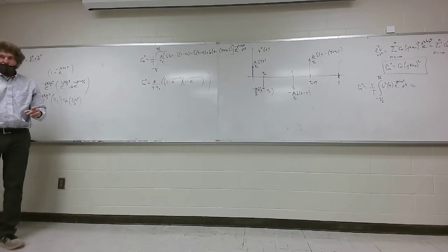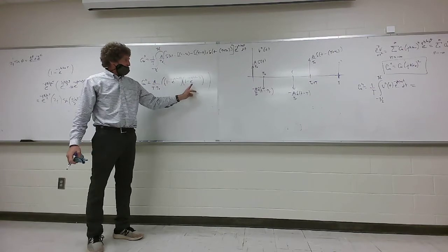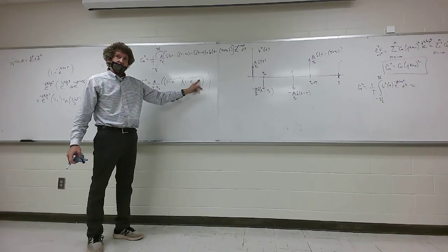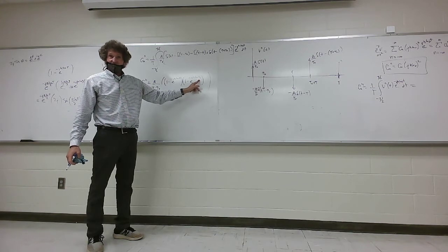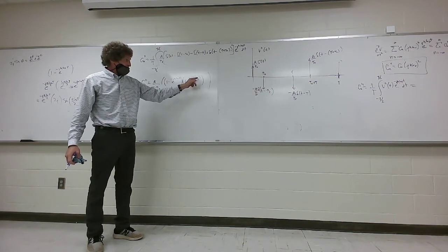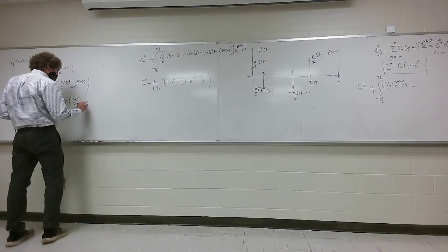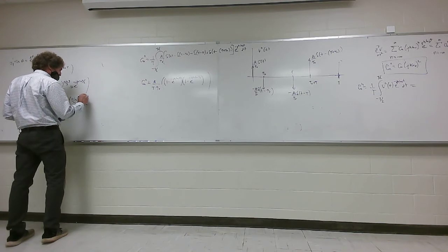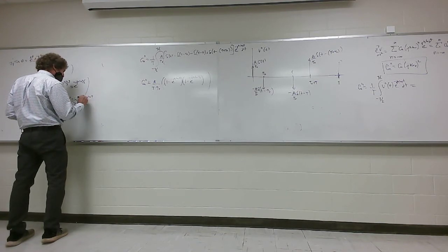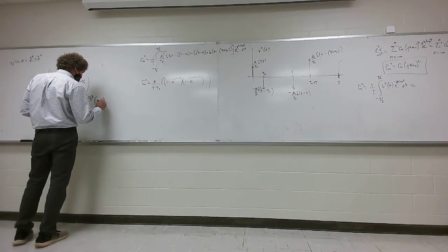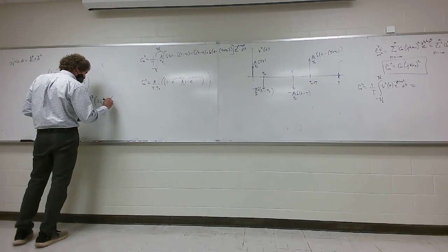Now, take a look at this next one. I'm almost done. What do you think happens there? Same exact signature, except instead of tau, you have tau rise, correct? Does everybody believe I can get a 2j sine of n omega naught tau rise over 2 out of it? You better believe it. So I take an e to the minus j n omega naught tau rise over 2 out. And now I have 2j times the sine of n omega naught tau rise over 2.